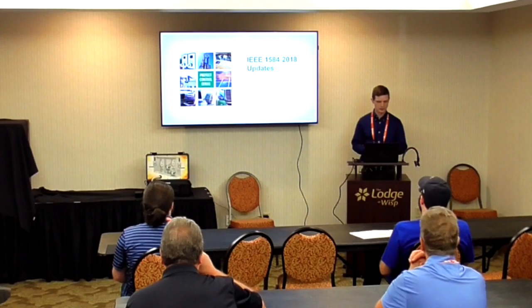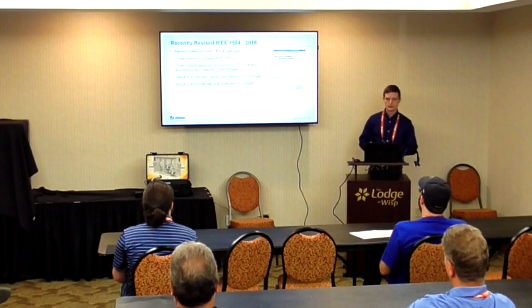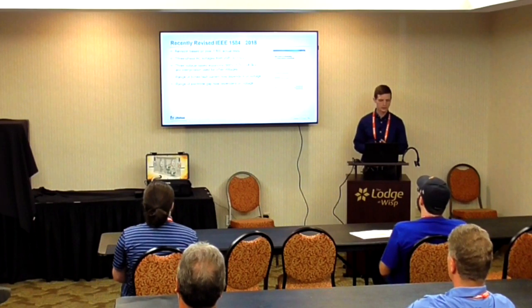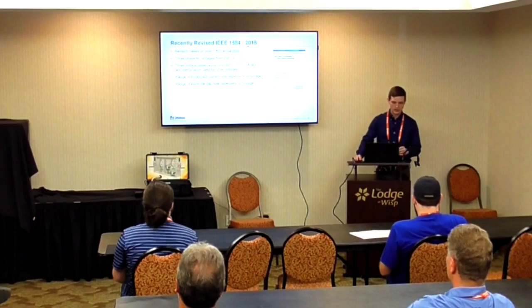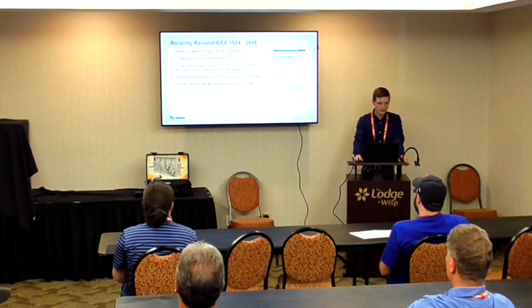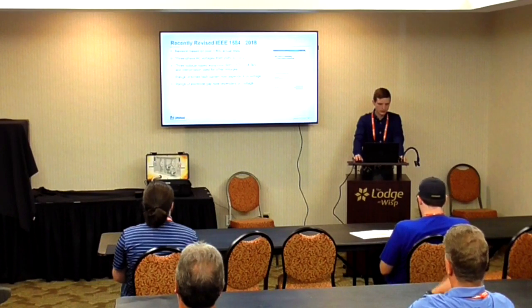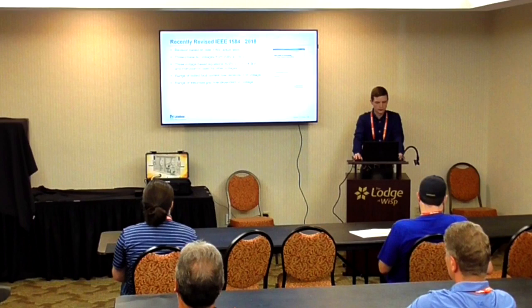Just going to jump into IEEE 1584. IEEE 1584, which as mentioned before is your guidance for arc flash hazard calculations, was updated in 2018. The new revision is based on 1,800 actual tests, so they did perform a lot of tests to actually get a lot of this information. And they introduced three-phase voltages, 208 V to now 15 kV, and they have this based on three voltage equations. So they have 600 volts, 2.7 kV, and 14.3 kV. There are methods for interpolating anything that is not one of these direct voltages.